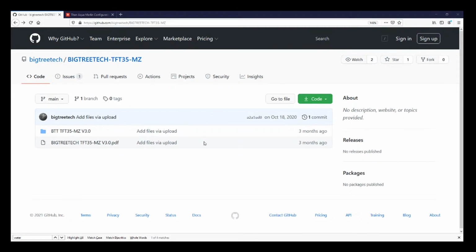On this board, we know that there's a TFT connection. So like always, we're going to take the connection. We're going to find out on the board where we need to connect it. It is probably right here. Yeah, it says RS232 and it's UART2.